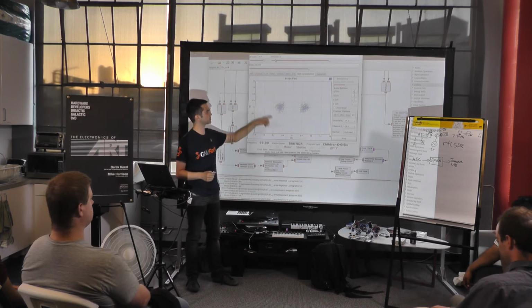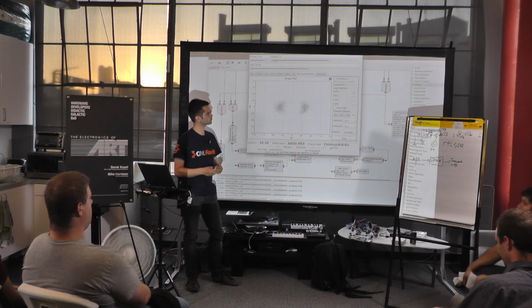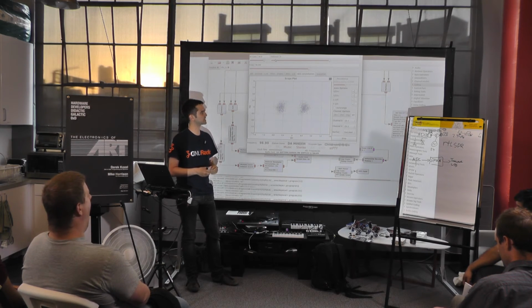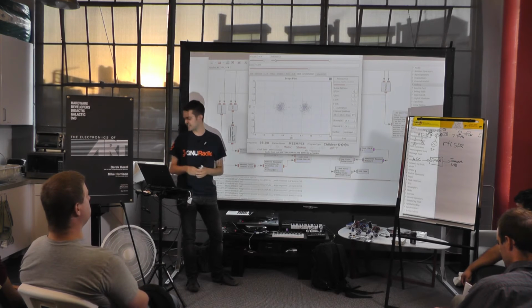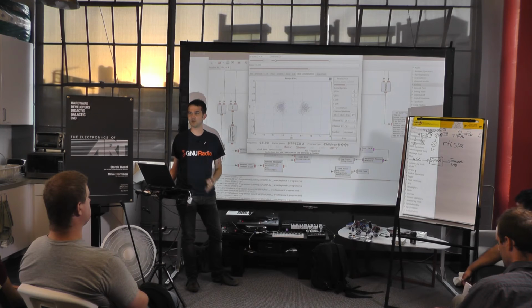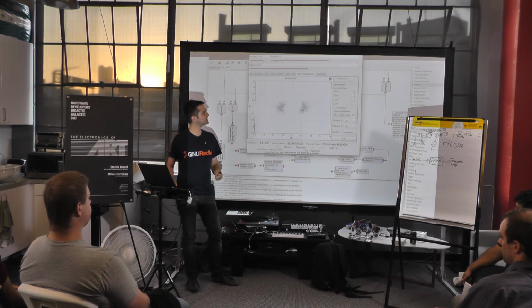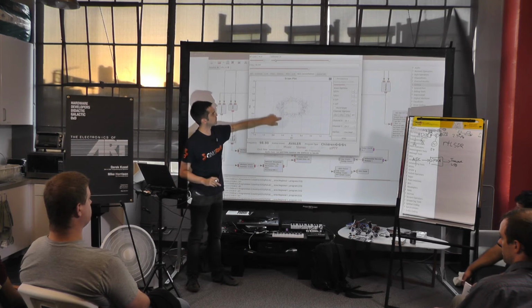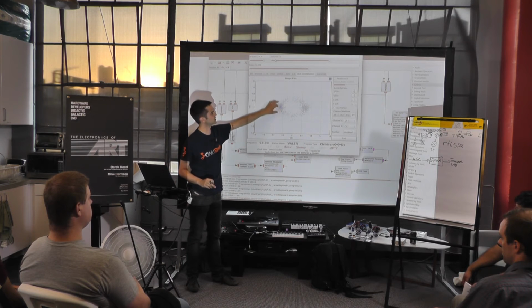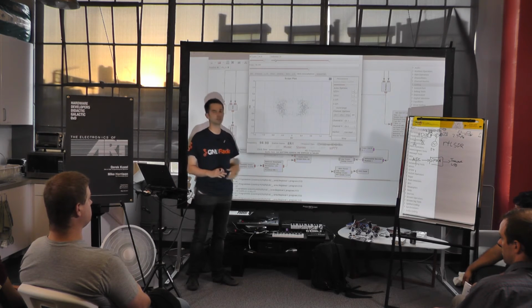So the phase information and the amplitude information gets a bit messed up. The frequency's a little offset. This thing is actually getting piping hot at the moment, and with temperature it'll change what frequency it's tuned to. So when we're seeing it clustered, we're seeing the noise, and when we're seeing that, it's losing its synchronization.